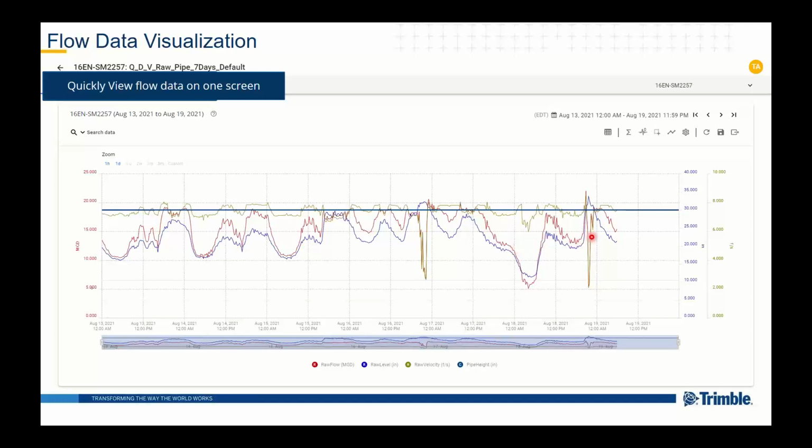A couple of days later, the same thing happened. There was a real large spike here. It must have been a pretty intense rain event, and you can track that the velocity backed up, went down below 2 feet per second for the 3-4 hour period.